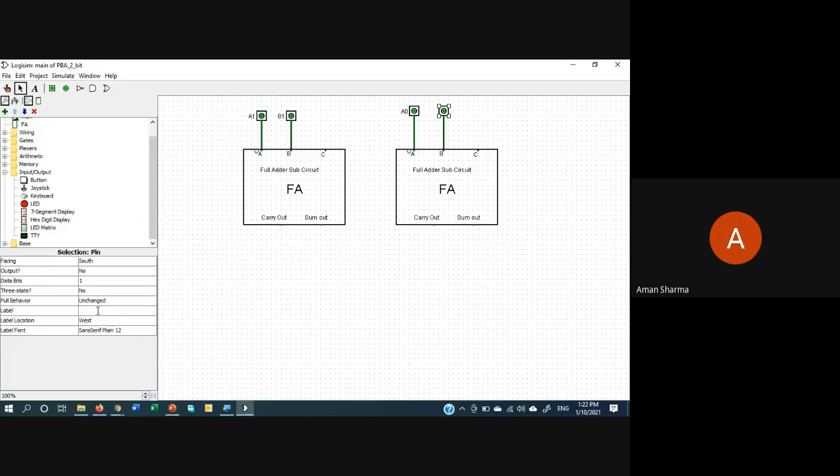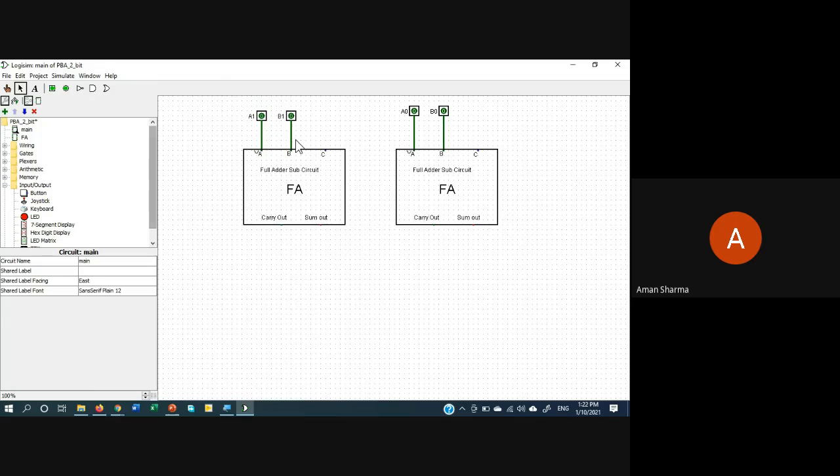The nomenclature that I'm using is the most common that you can find in your textbooks. And for this, let me say this is C0. As this is the initial full adder, it will always be connected to the ground if not specified. So let me assume for this instance the initial carry is always 0.